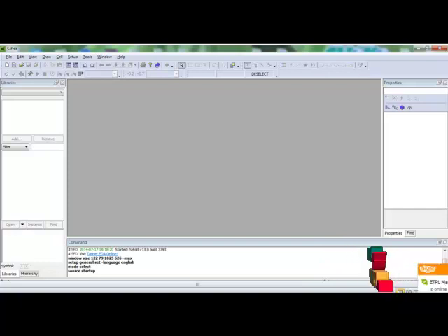In T-Spice, we can export the code of the designed circuit. So we can work on the code in T-Spice and modify it as per our requirement. So we are using S-Edit for the circuit design, T-Spice for the extra modification, and W-Edit for the output design and analysis of the output waveform. So this is the tool we are using here.